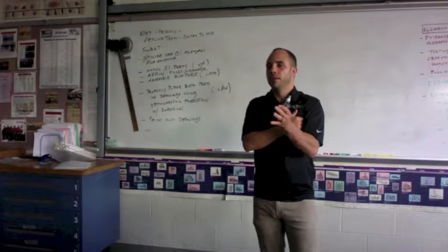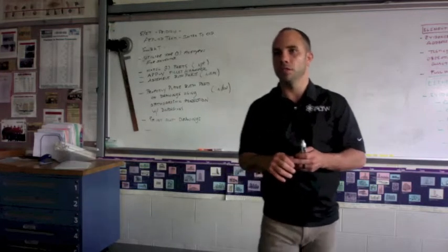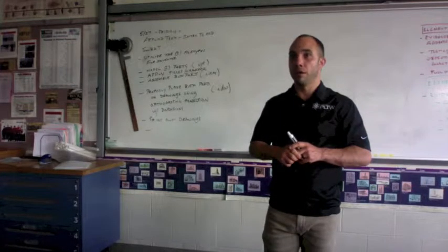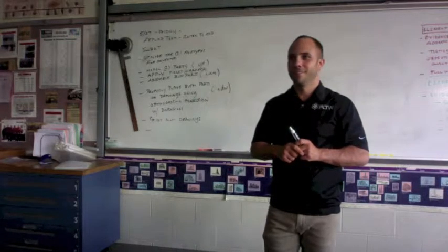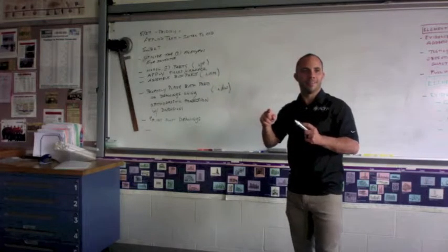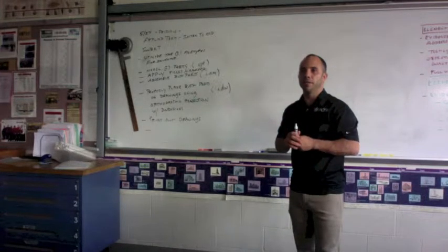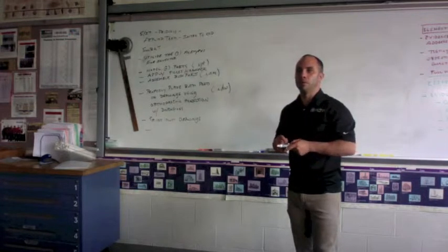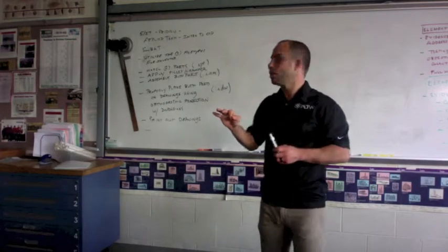So they're different file types like dot something, right, associated with those. You guys remember what they were? Anybody? IDW. What's a part? Somebody raise your hand. IPT. IPT, assembly. Ethan, what's an assembly? What's a drawing? Somebody already said IDW. So assembly is IAM. So those are three file types.